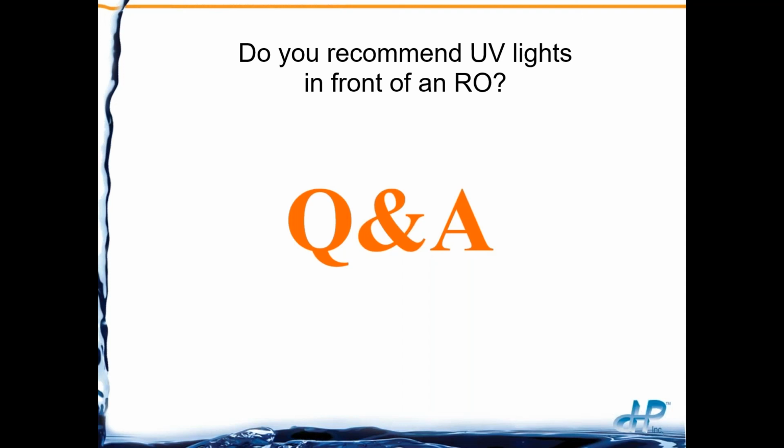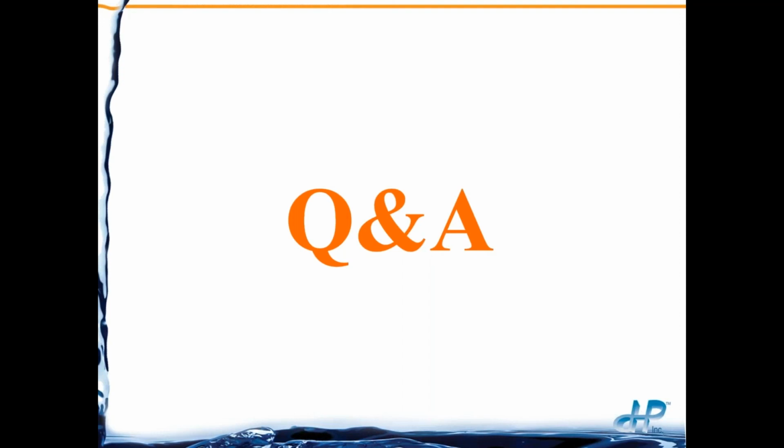So our experience with UV lights in front of an RO system is that they won't necessarily control the bacterial growth in that RO system. There is a time and place for UV lights. We just don't agree with trying to control bacteria in the RO system itself. So we have never had any luck with it.